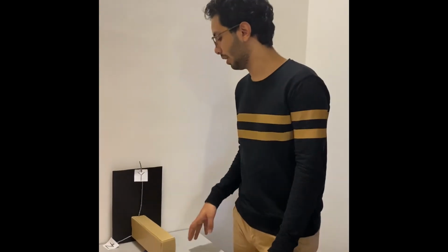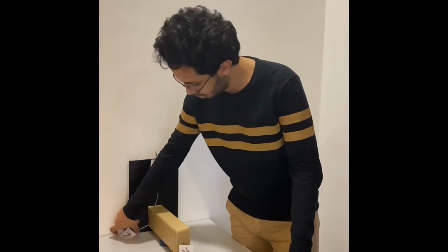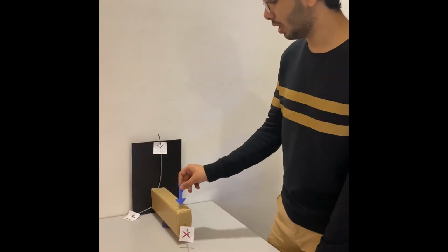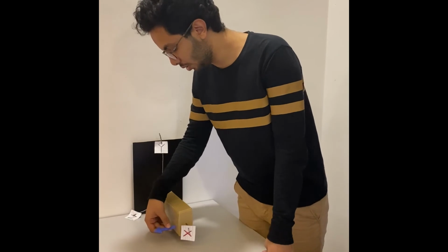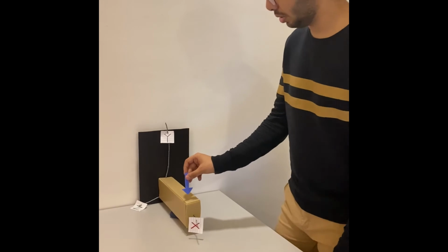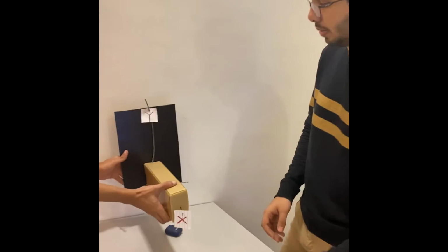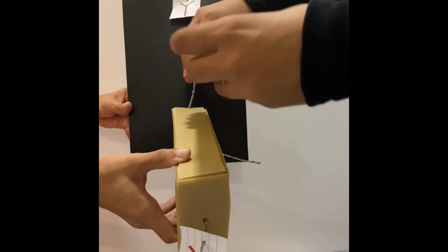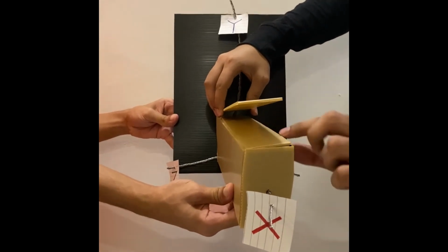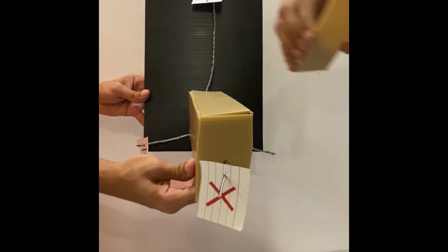So now I will be explaining how the stresses react in our cantilever beam. So this is our y-axis, this is the z-axis, and here is our x-axis. And we have two loads, the 7,500 Newton, and the other load acting in this direction with 2,000 Newton. Due to the 7,500 Newton load, there will be a deflection in our cantilever beam. So our original plan is this one, and this is after the deflection. This is the distance that is caused by the load.